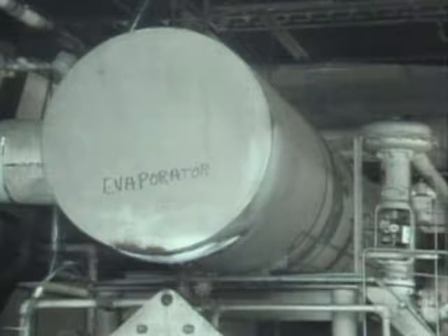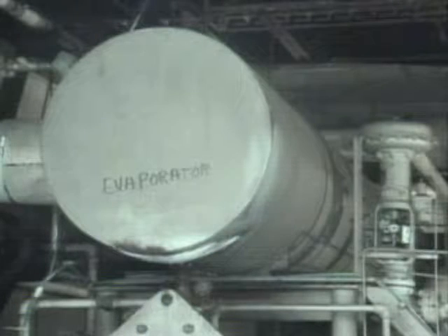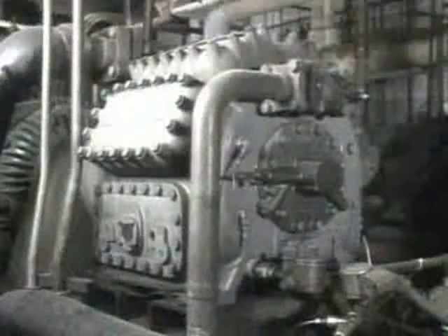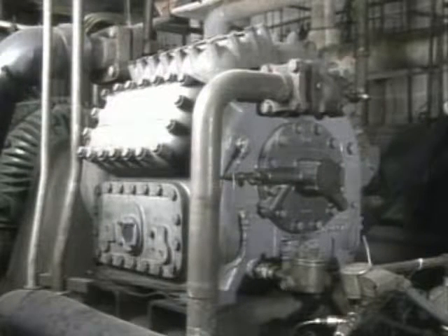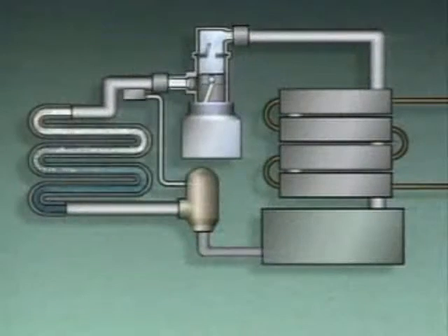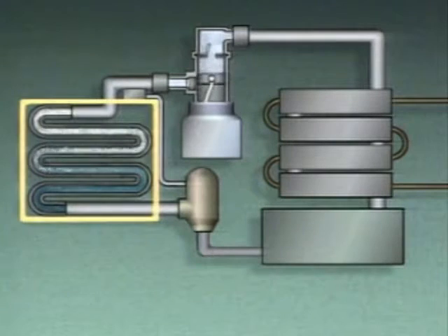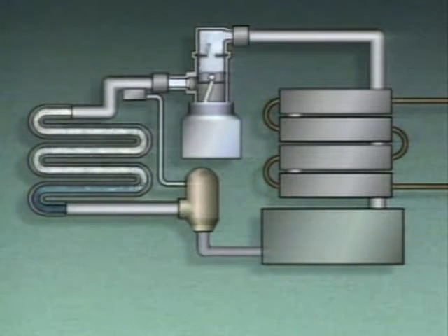One place where this is a problem is in the evaporator. When refrigerant flow through the evaporator is too low, less heat will be removed from the substance being cooled. This will cause the temperature of the substance being cooled to increase. The compressor may also provide an indication of a low flow problem. In a system with a reciprocating compressor, reduced refrigerant flow causes the pressure in the evaporator to decrease.